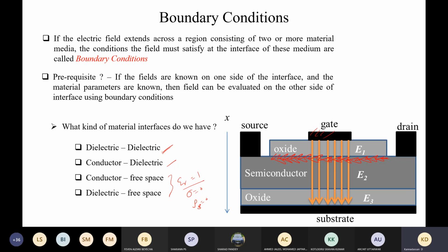There are theories that this depletion region happens because of attraction of charges from here to here. But before applying the field itself, there is an existence of some charges. The same theory, when you write in terms of an energy band diagram, with, let's say, the conduction band, when you draw it, you will get this kind of charge. So there is already an existence of the electric field even before the application of the field itself, which we call equilibrium.